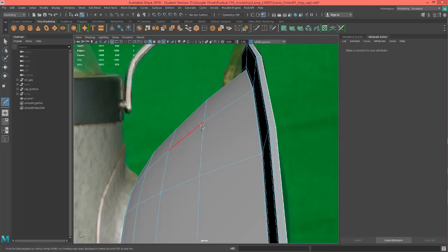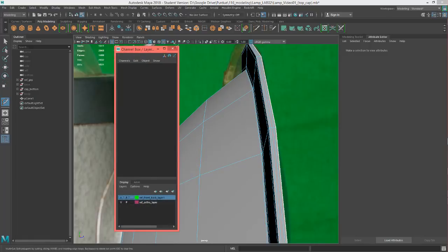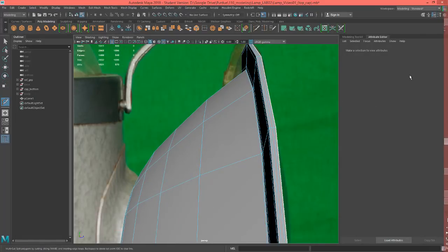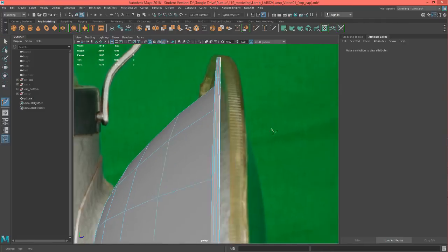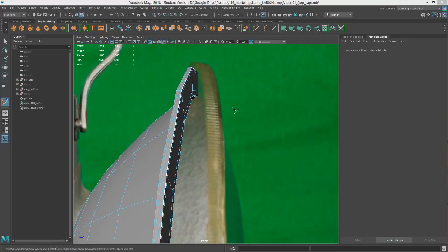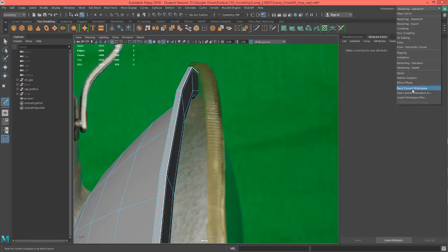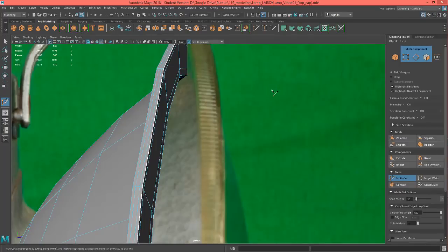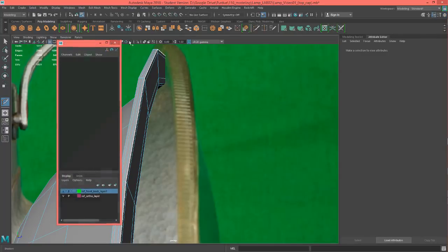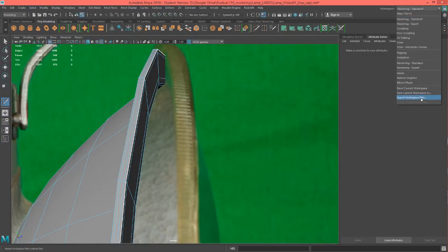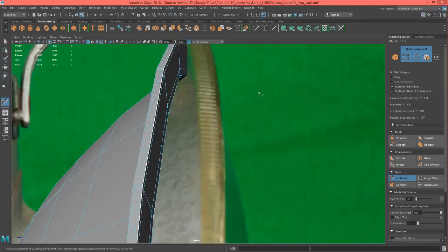Let's go back to modeling, or Maya standard. All right, Maya standard. So I'm getting this problem that's happened a few times when I'm going back to Maya standard and I want my attribute editor to come out. It's like it's keeping it almost locked, like it was in a different mode, and I don't like it like that. So if that happens, I can reset my current workspace. So I can do that, and now if I hit Control A, oh, I lied. That usually fixes it. So let me see, save current workspace, reset workspace. That usually works, but apparently this time it did not.